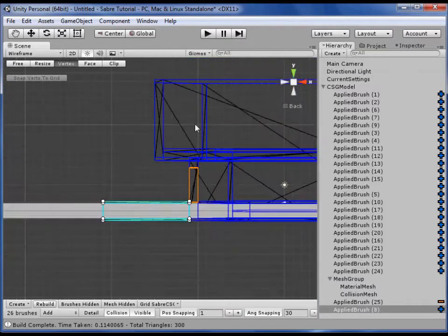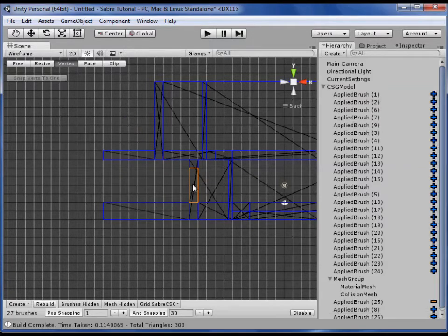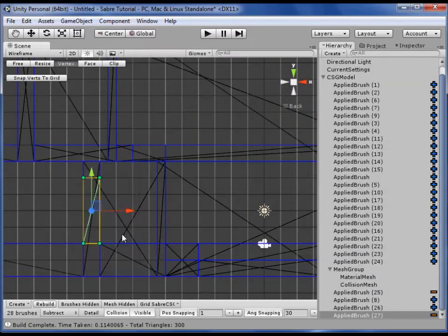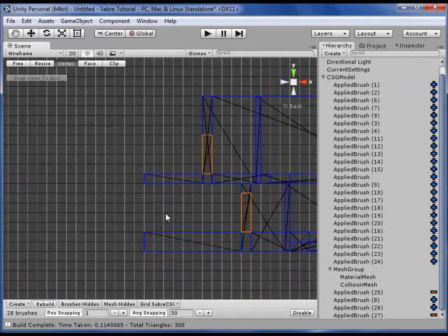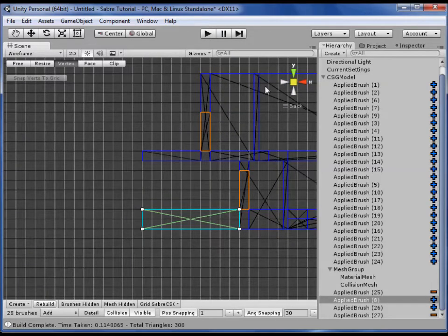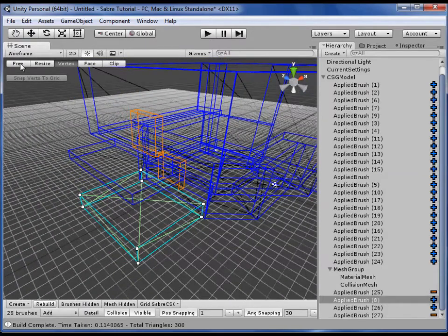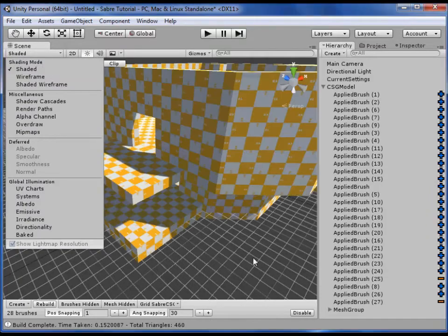Okay. Let's create a platform for the top floor. That will be a little bit smaller. Let's also, while we're at it, go ahead and just drag that doorway to the top floor. Okay, so now let's go ahead and switch to perspective mode for a second, and rebuild, and shaded.